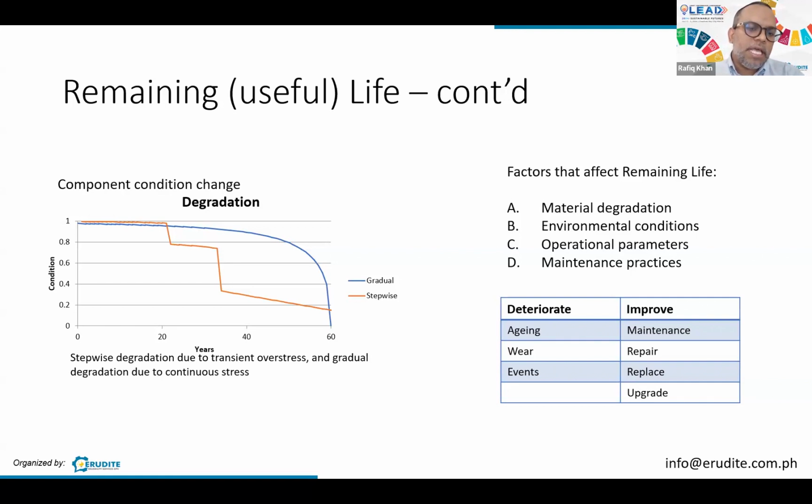But degradation in the insulation can happen quite abruptly. It can be also a stepwise drop. And things like transient overvoltage, when you have lightnings or switching, those can result in this kind of pattern. External mechanical impacts, let's say when they do some form of handling during installation, and you have displacement of parts inside a component, then you can also have a stepwise decrease in the